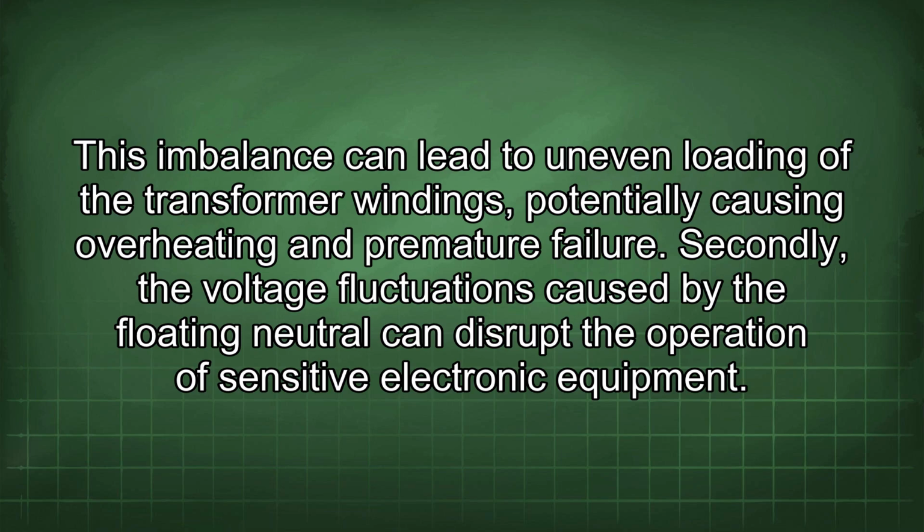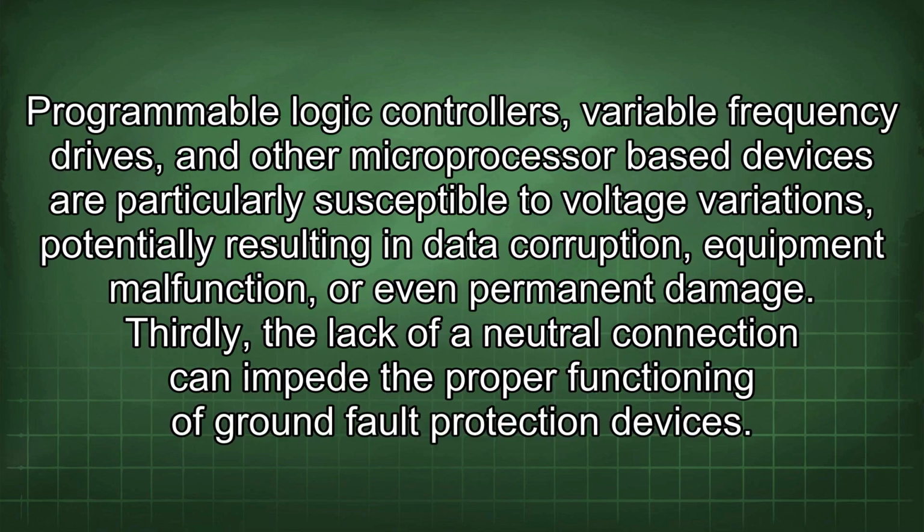Secondly, the voltage fluctuations caused by the floating neutral can disrupt the operation of sensitive electronic equipment. Programmable logic controllers, variable frequency drives, and other microprocessor-based devices are particularly susceptible to voltage variations, potentially resulting in data corruption, equipment malfunction, or even permanent damage.